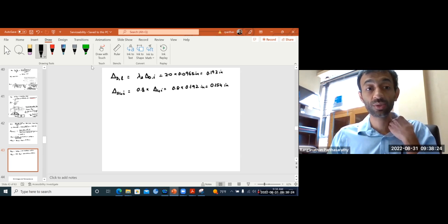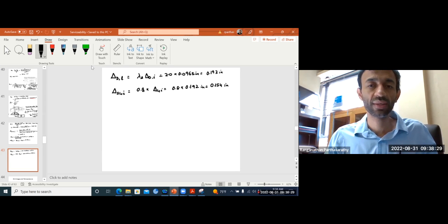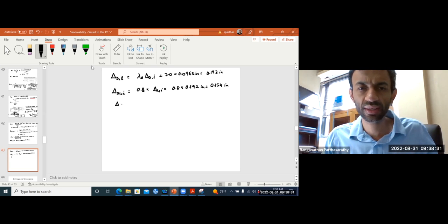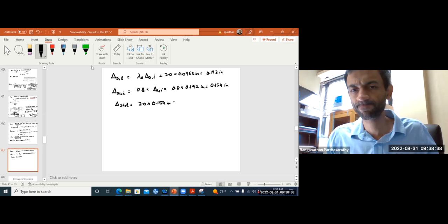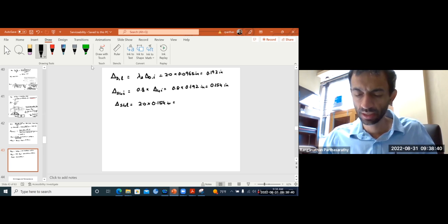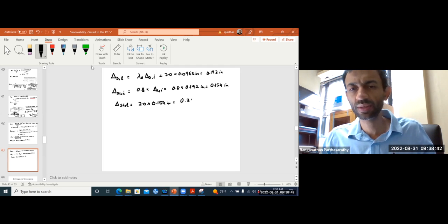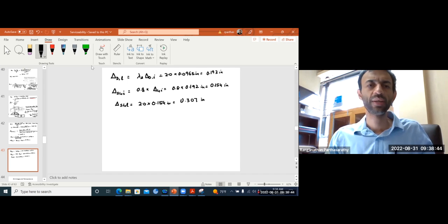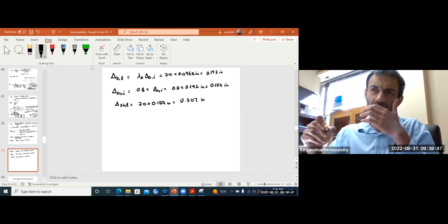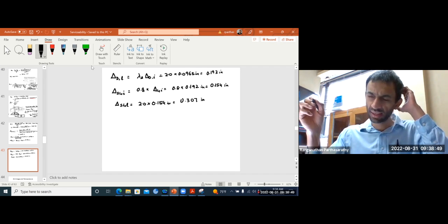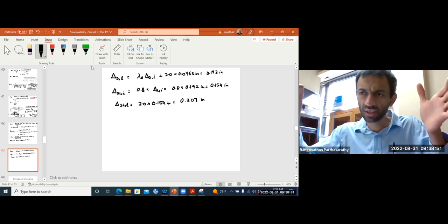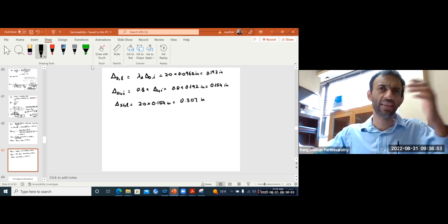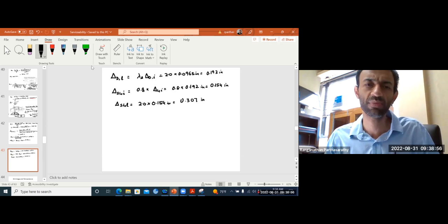Okay. So now we have delta D long term, delta SL initial. So delta SL long term will be 2 times of this, 0.307. Okay, so what's the everything except delta dead load initial? That's what will count for the partitions because they came in after the construction happened.